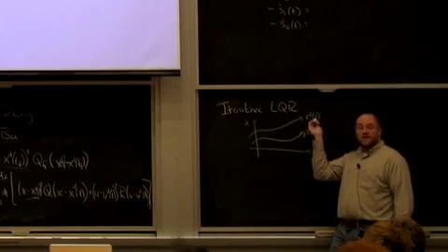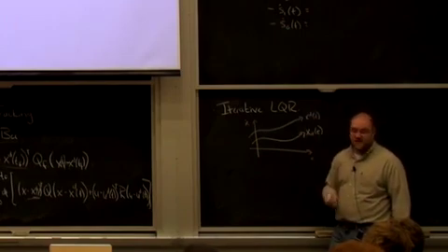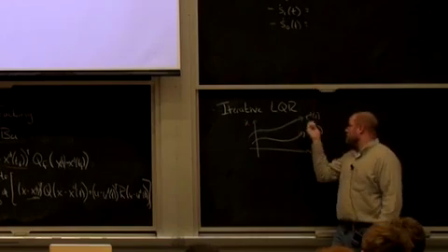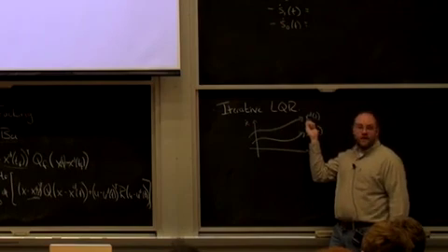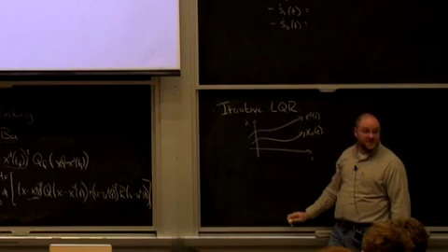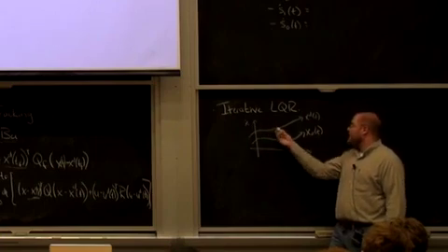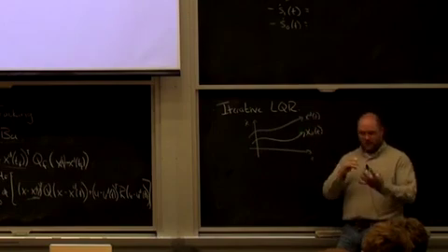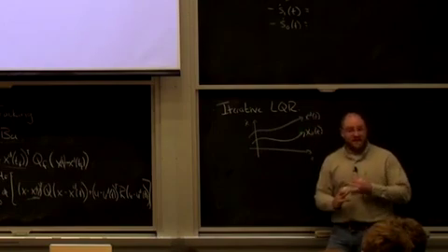So I have no guarantees that x desired is a feasible trajectory. In fact, in many cases it's not. For instance, x desired might be at the goal at all times, right? If I came up with a perfectly feasible x desired trajectory, I probably wouldn't be running an open loop solver, right? I want to get as close as possible to the x desired while potentially minimizing cost and respecting the dynamics of the system.